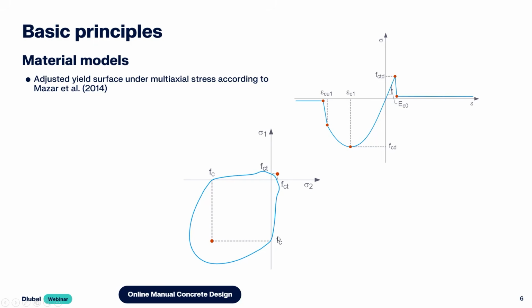In the biaxial tension region, so tension in both directions of an element, the strength of concrete is reduced. See here. As a result, the failure surface is reached at a lower stress. Crack formation follows. In the compression region, on the other hand, an increase in the permissible stress is possible for elastic behavior, as shown here.